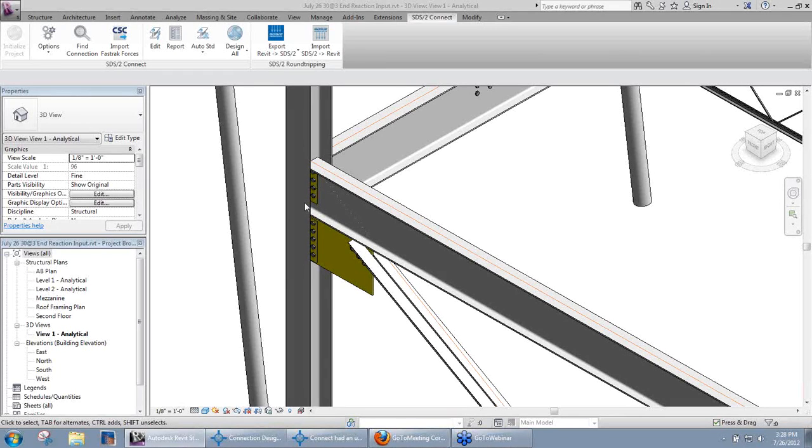If the option that I showed you to use Revit end reactions is turned on, we look to the end reaction total and start reaction total parameters, and if there is a value present in those parameters, we'll apply that to the appropriate beam connections. If there is not a value present, we default back to calculating the automatic load like I explained at the beginning of the webinar, or you can input whatever you need there.